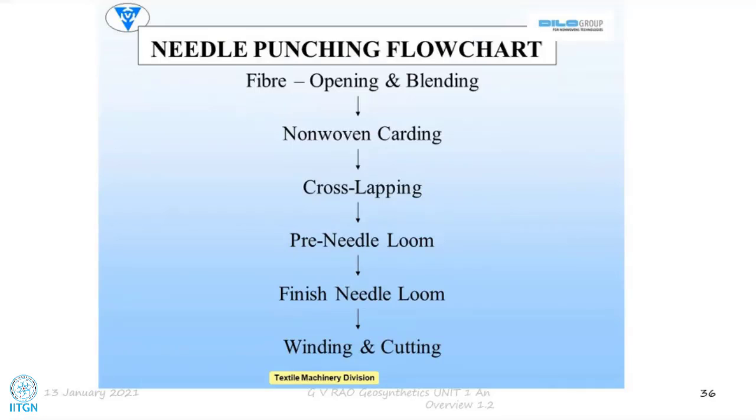That means all the what we call staple fibers are coming in one direction. That is why, when I showed you how the conveyor belt is feeding into the needle punching system, I said that they are all more or less linear and horizontal only. Now let us not imagine that all of them are just coming horizontally in the longitudinal direction of the cloth, that means machine direction. That is one way of laying them.